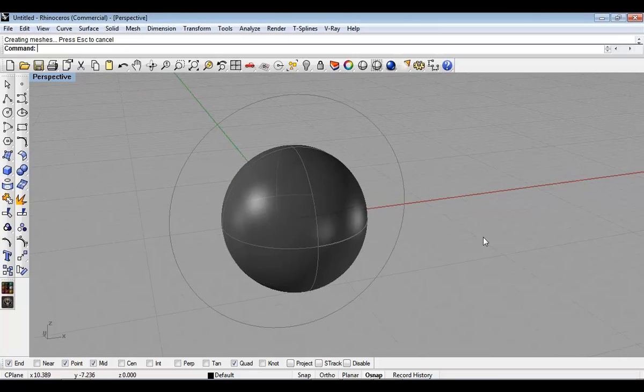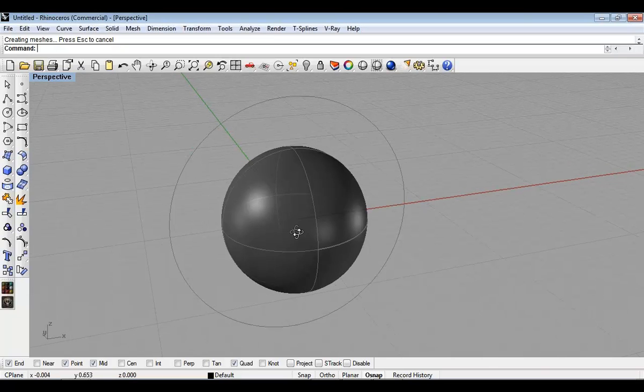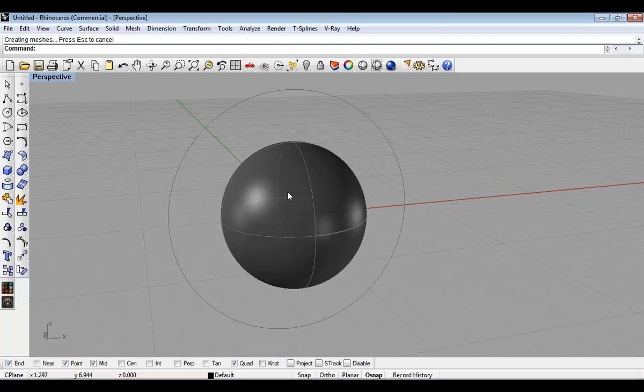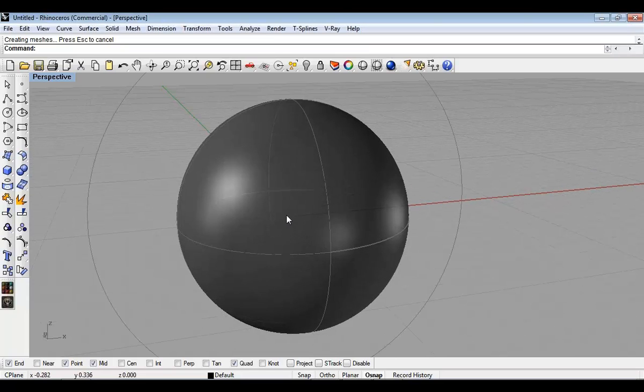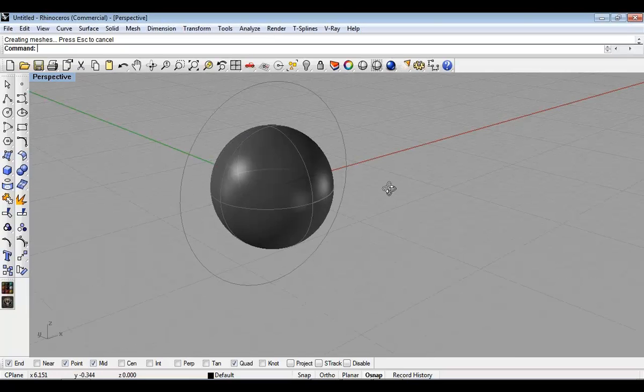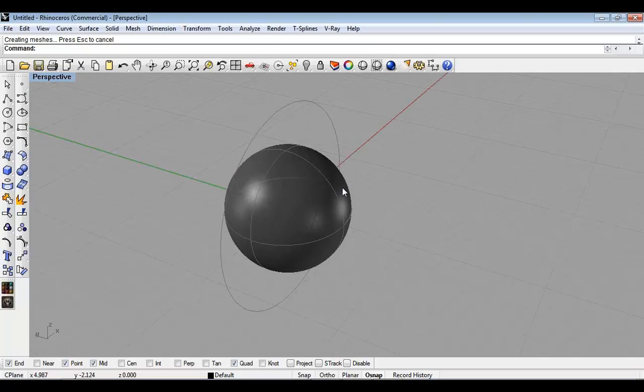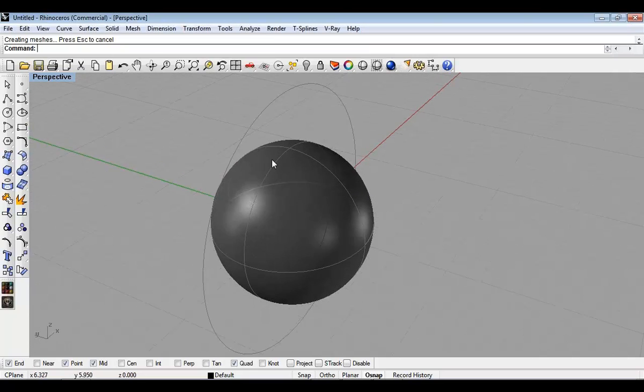All right, so what we're going to start with, also for people who don't use Matrix, when I say the word F4, the Matrix program has world origin, which is 0x 0y 0z, coded to the F4 key. So when you press F4, it will start whatever you're drawing from the world origin center of axes. I know that in a couple of my videos I say something from F4, and people go, what are you talking about? So that's what that's about.